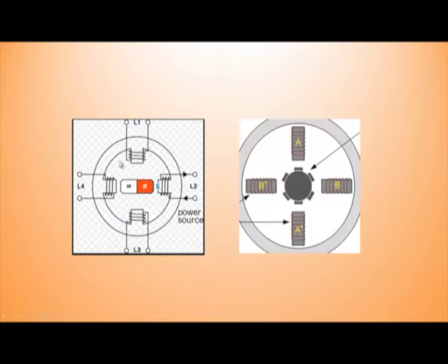This rotation is step by step, because there are four states: first attraction here, then this way it keeps rotating. The rotation may be in the clockwise direction or in the anti-clockwise direction. The other one is the variable reluctance stepper motor. Here we use only iron with teeth. Some teeth are projected on the rotor part, and the stationary parts are coiled to supply the electrical signal.